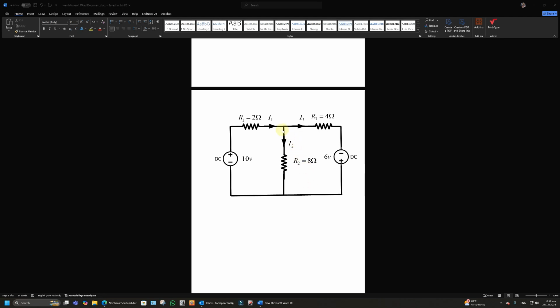There are other ways you can do it. You can use nodal analysis, but that really is the same thing. You can call that node there VA, let's say, and sum the currents into there. Then you get 10 minus VA divided by that equals this current from that current, which is Kirchhoff's current law, really, nodal analysis, but written in terms of the voltages.